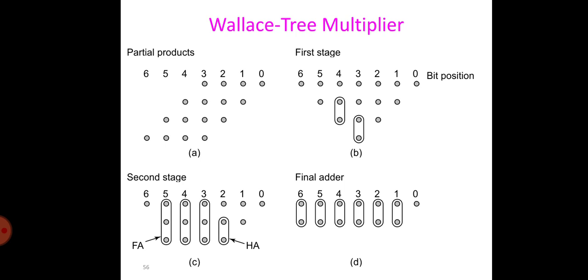The number of full adders needed for this operation can be reduced by observing that only column 3 in the array has to add 4 bits. All other columns are somewhat less complex, where the original matrix of the partial products is reorganized into a tree shape to visually illustrate its varying depth. The challenge is to realize the complete matrix with the minimum depth and the minimum number of adder elements.